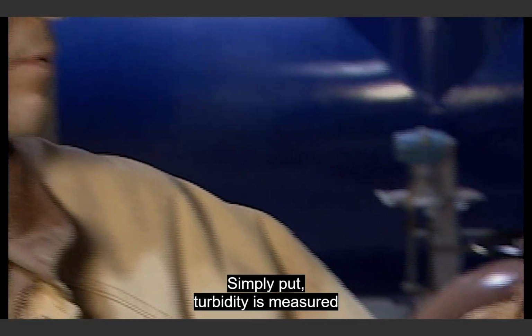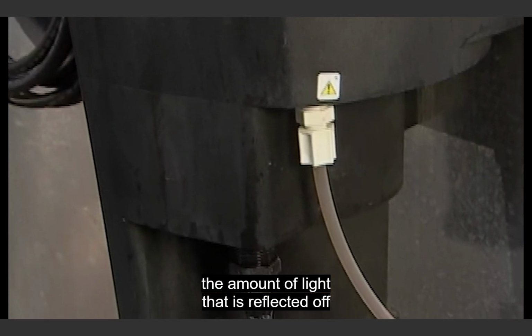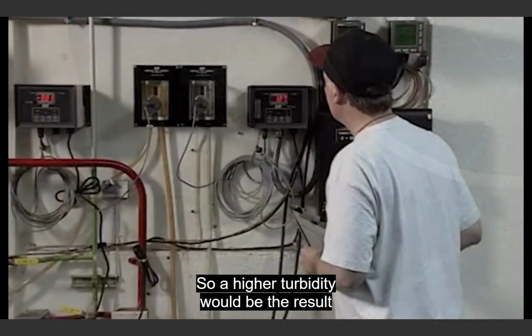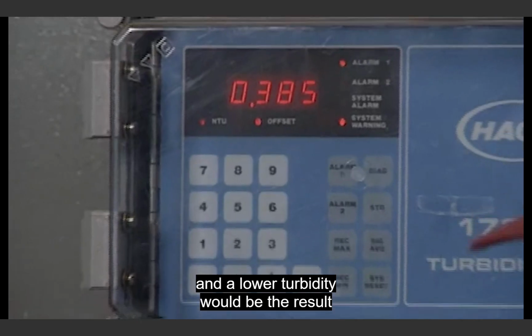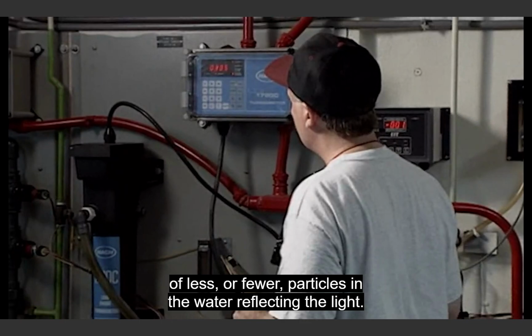Simply put, turbidity is measured by shining a light through water and measuring the amount of light that is reflected off the particles in the water. So, a higher turbidity would be the result of more particles in the water reflecting the light, and a lower turbidity would be the result of less or fewer particles in the water reflecting the light.